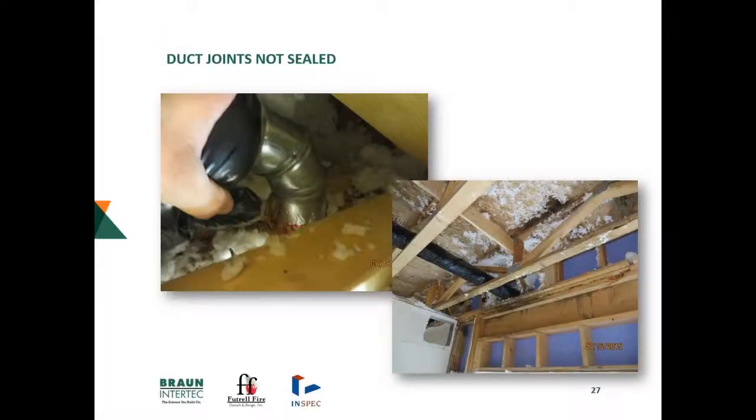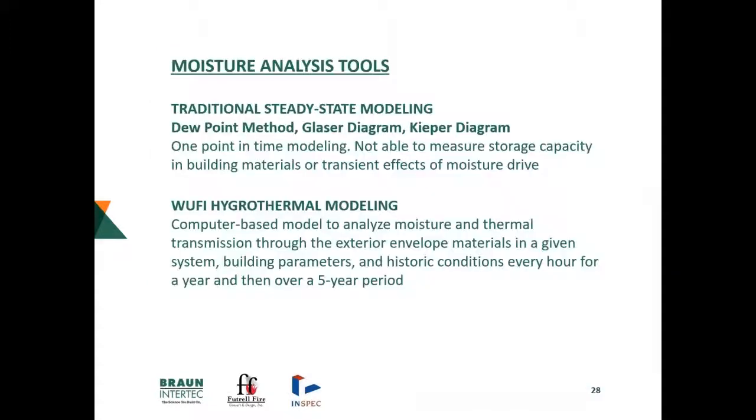We also, in some cases, saw duct sealing not done, elbows not sealed, some insulation missing on some of the ductwork, and that's not good either. That's certainly adding to the entire flavor of moisture in that space. But that's also very important to be constructing correctly as well. And then to the bottom right, again, that's depicting that unsealed location of the duct exiting the building itself.